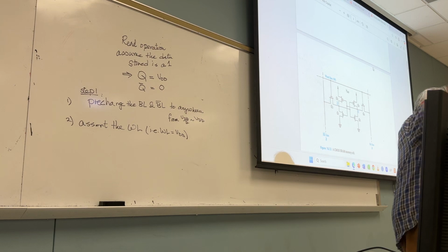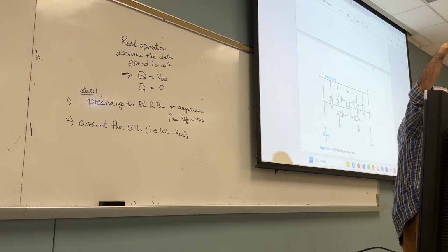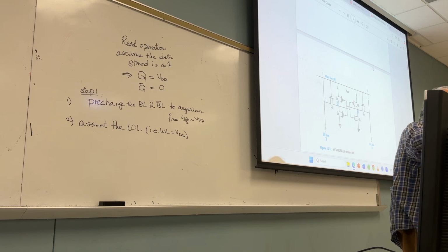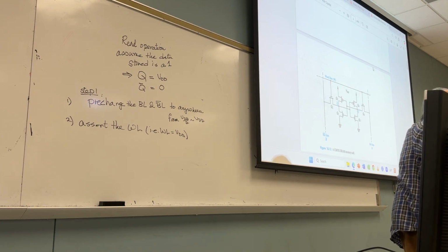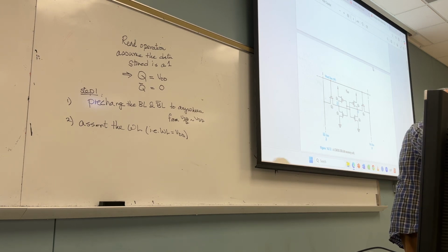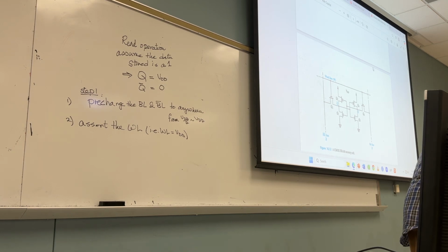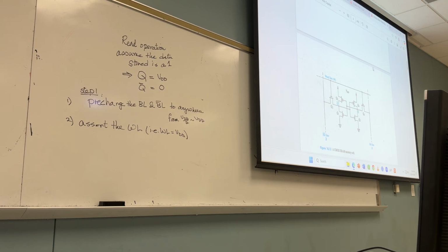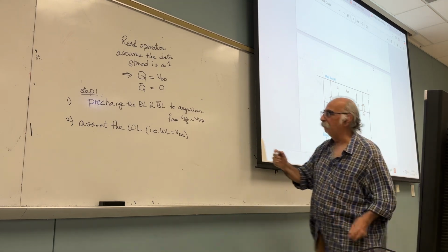Remember, all the word lines are pre-charged to 1. And then only that word line is to remain 1, and the other word lines need to go to 0, because I'm selecting this NOR based, active high. Did you get it? Yes. We discussed this one last time. Okay, what will happen?